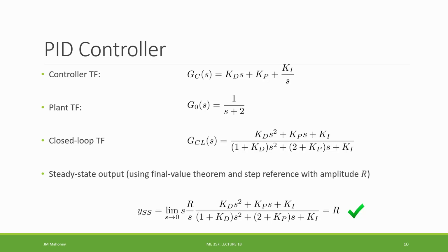So we're going to take this on to the next step: what gains should we choose so that we get the behavior that we're actually interested in? But at least we know that given enough time, it does drive the error to 0. If we look at the poles of sY(s), once again, we have to make sure that they are all in the left half plane.